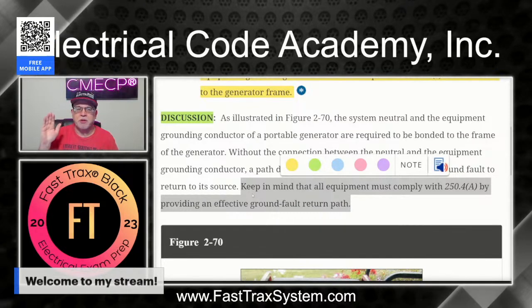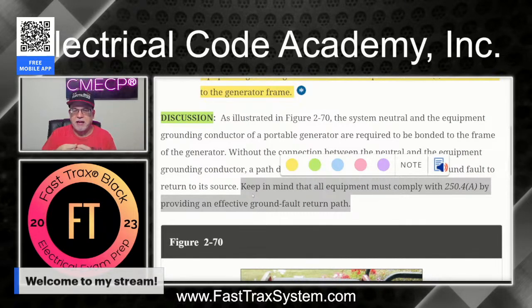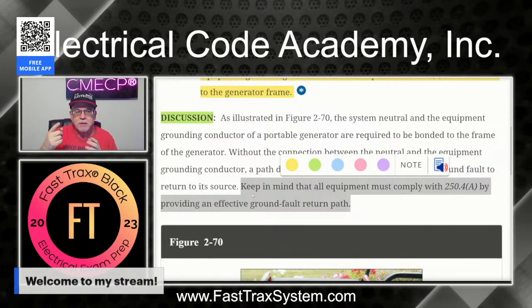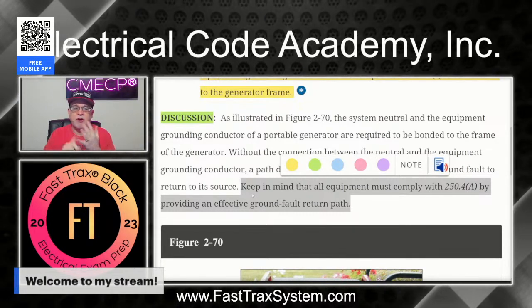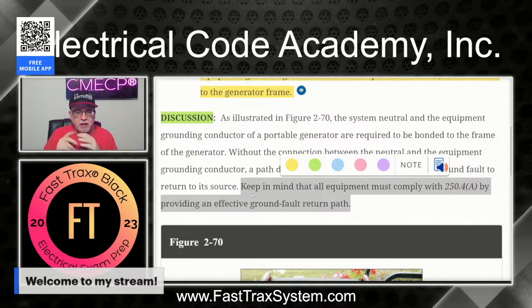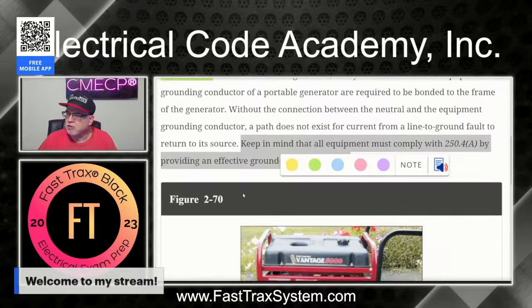We have our receptacles with our equipment ground terminals, connected to the frame. The frame is connected to the neutral point on this generator so that we can complete that cycle and allow the overcurrent device to function and allow the GFCIs that are typically built in to these portable generator setups to function. All right, so let's look at this real quick.